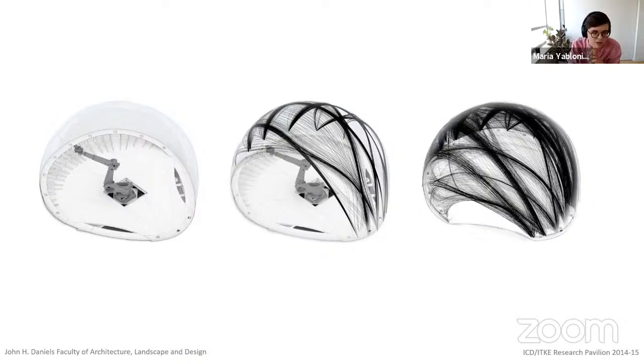So we looked at this process and, inspired by it, we developed an architectural version of that, or rather an architectural abstraction of this construction sequence, if you will. What we came up with was an inflatable soft pneumatic membrane that served as a formwork for our final pavilion shape. Inside of this pneumatic framework, we have a robotic arm that sits inside and can reach every single point on the membrane. The robotic arm is equipped with a custom designed end effector that lays pre-impregnated carbon fiber onto the surface of the membrane.